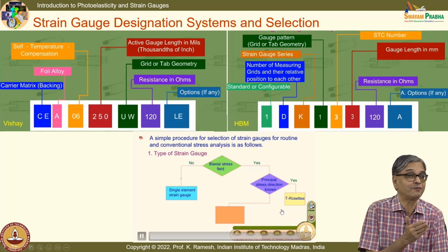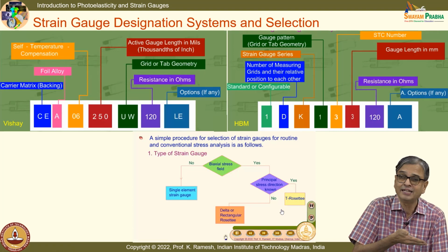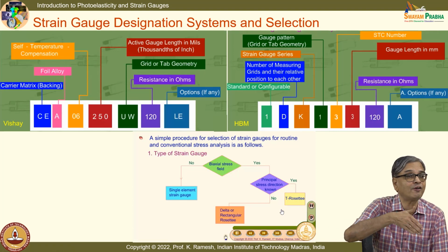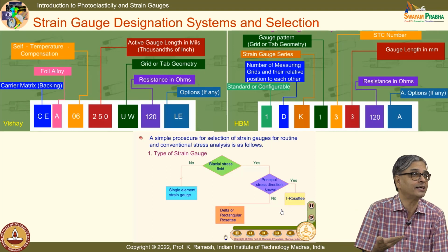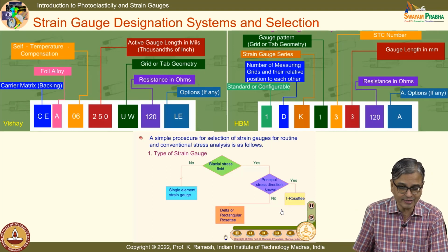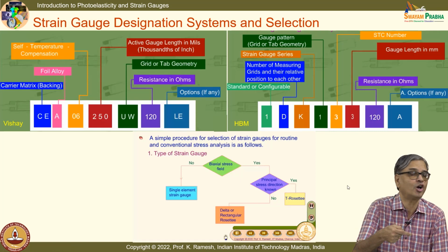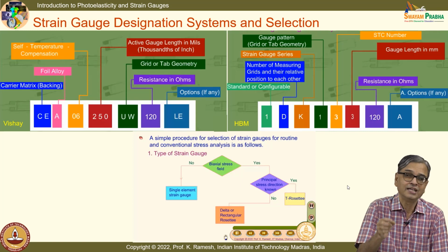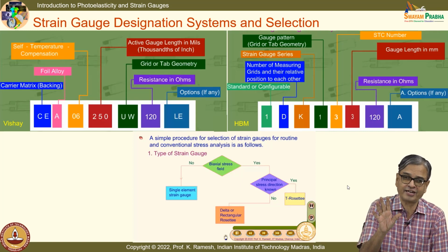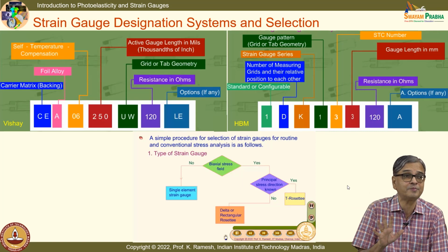We have looked at what brittle coating is. In the brittle coating, when I have a crack pattern, tangential to the crack and perpendicular to the crack, you know the principal strain directions. When a principal direction is known, I can paste just one strain gauge, or 2 strain gauges, to make the strain measurement. Otherwise, at a point I need 3 strain gauges. If I need 3 strain gauges, I need 3 instruments to measure the strain. Is the idea clear? 3 Wheatstone bridges are required.